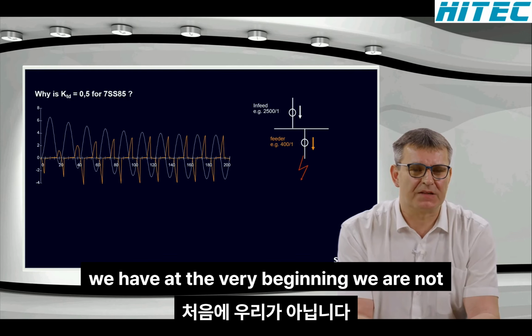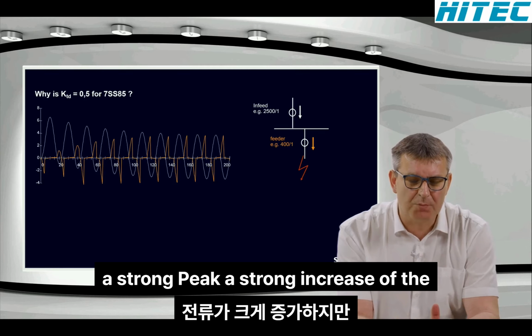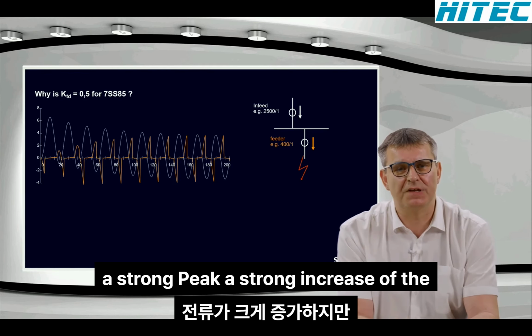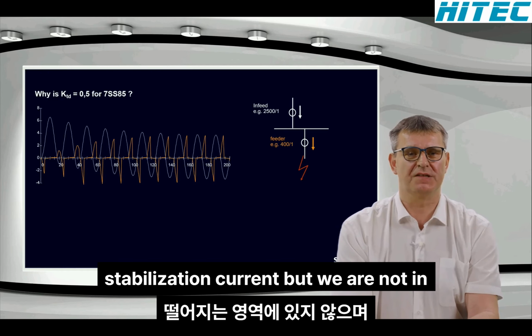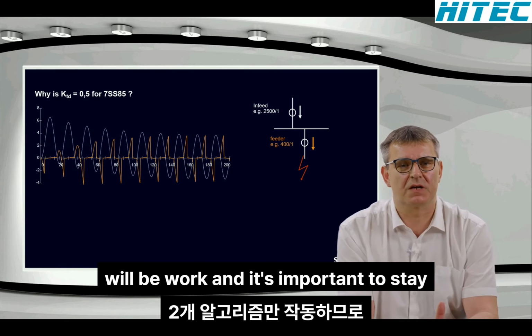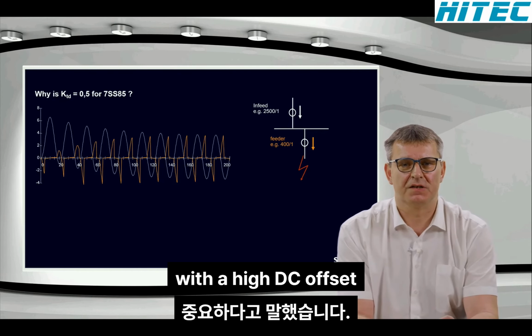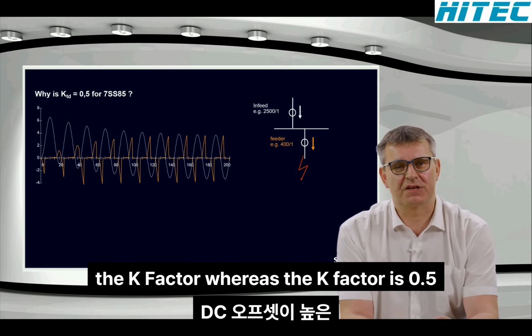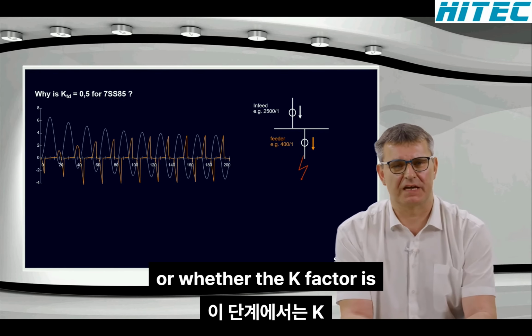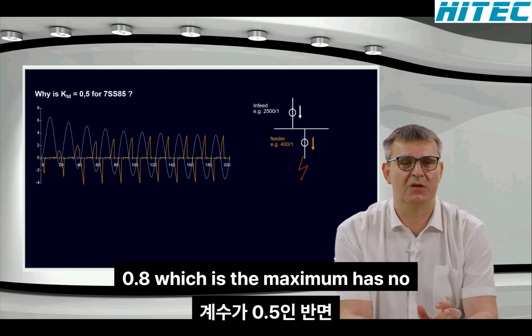we have a strong peak, a strong increase of the stabilization current, but we are not in the tripping area, and that's why the 1-out-of-1 algorithm will be blocked, and then only the 2-out-of-2 algorithm will work. And it's important to say that in this phase with a high DC offset, whether the K factor is 0.5 or whether the K factor is 0.8, which is the maximum, has no importance.